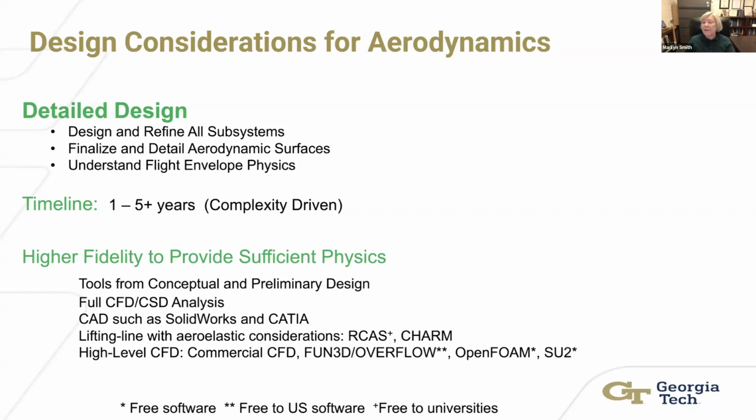We'll talk about this in a minute with turbulence models. This is where you're going to go to either detached eddy simulation or a full up subgrid scale large eddy simulation, but probably in the wake, you're not going to do it right to the surface. You don't have the computational resources for that. But you will be looking at more detail, making many more of those runs.